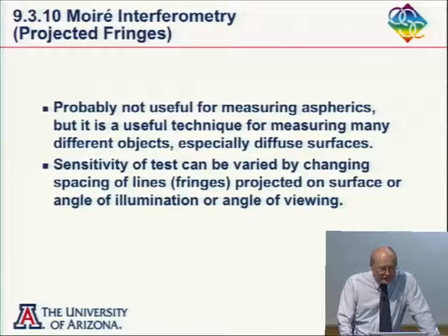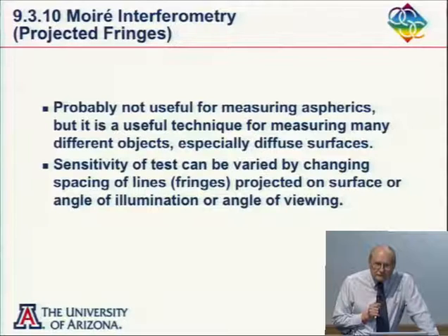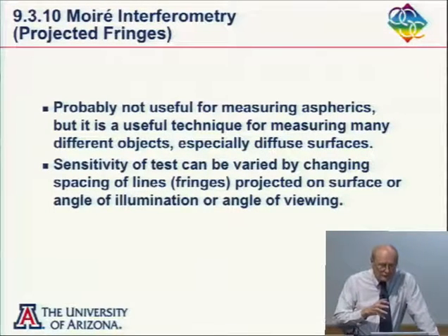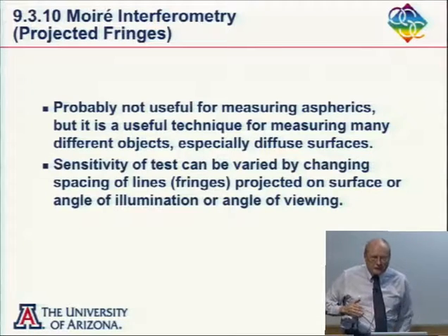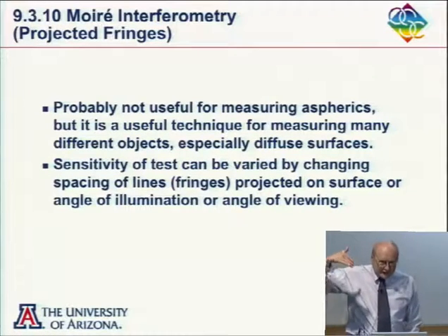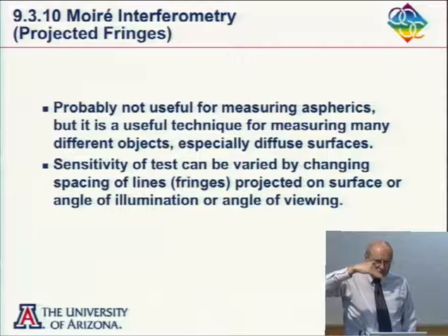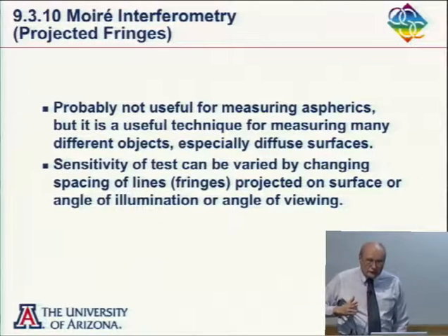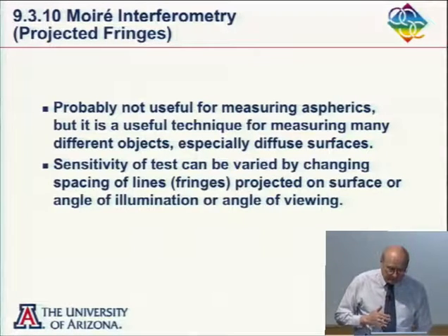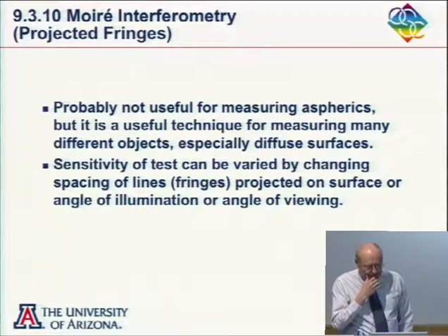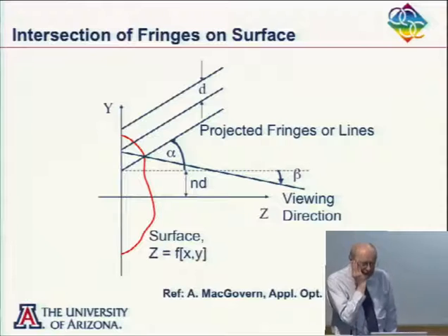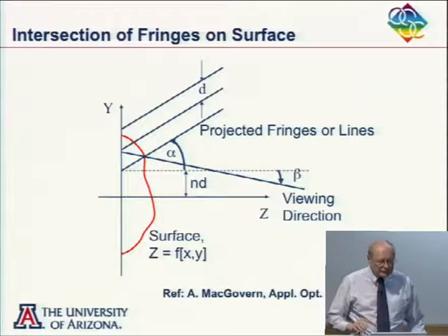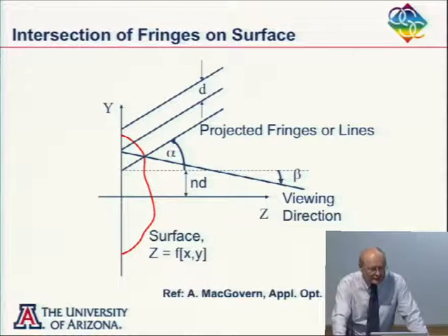Okay. It's a test where you're going to vary the sensitivity by changing the spacing of the lines, or sometimes they're fringes instead of lines. Or you can change the sensitivity by changing the angle at which you're projecting the lines onto the surface, and/or changing the angle at which you're viewing the lines. So it's pretty flexible. So we'll go through here and see just how this works.